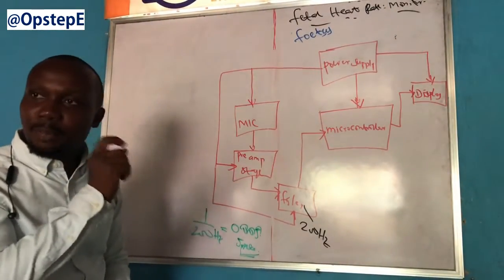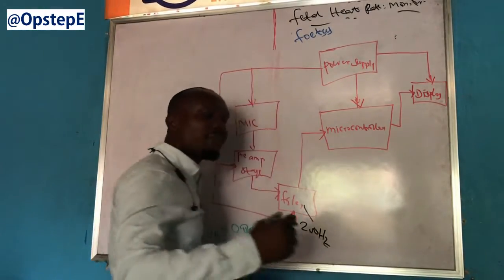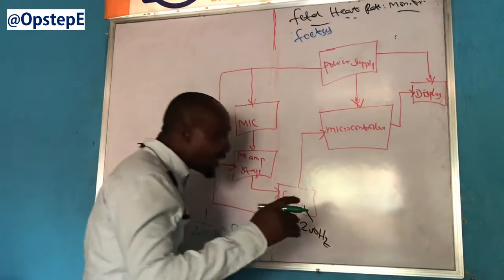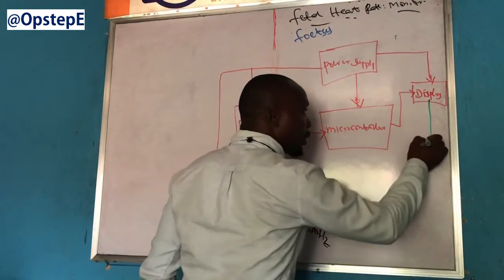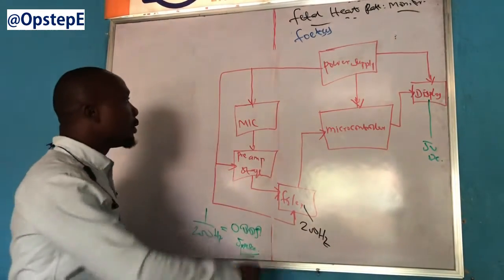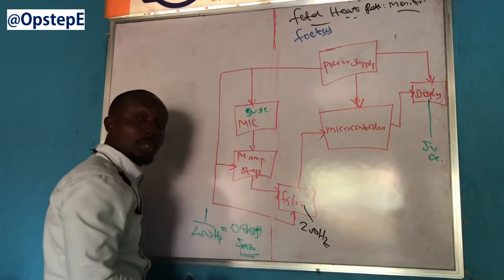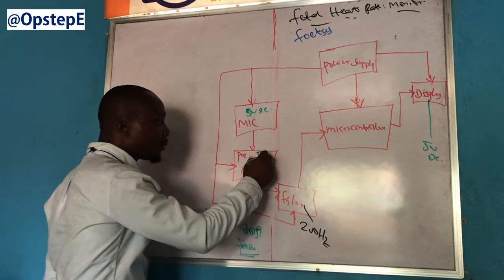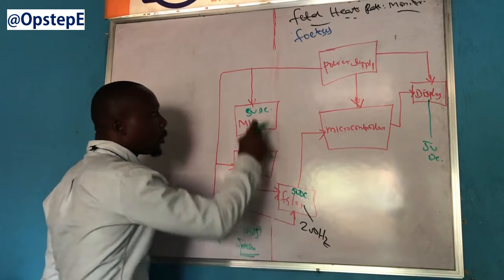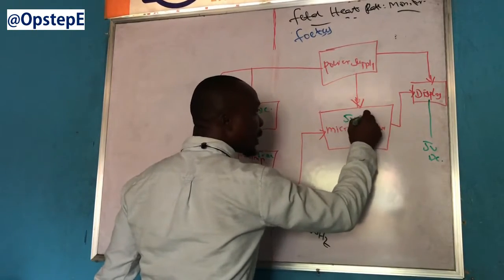For the display we are going to be using, we had agreed that we want to write on an alphanumeric LCD. LCD will be liquid crystal display. That display requires 5 volt DC to operate. The microphone requires 5 volt DC to operate. So also is the preamp and then the filter stage. 1, 2, 3, 4, including the microcontroller itself requires 5 volt to operate.